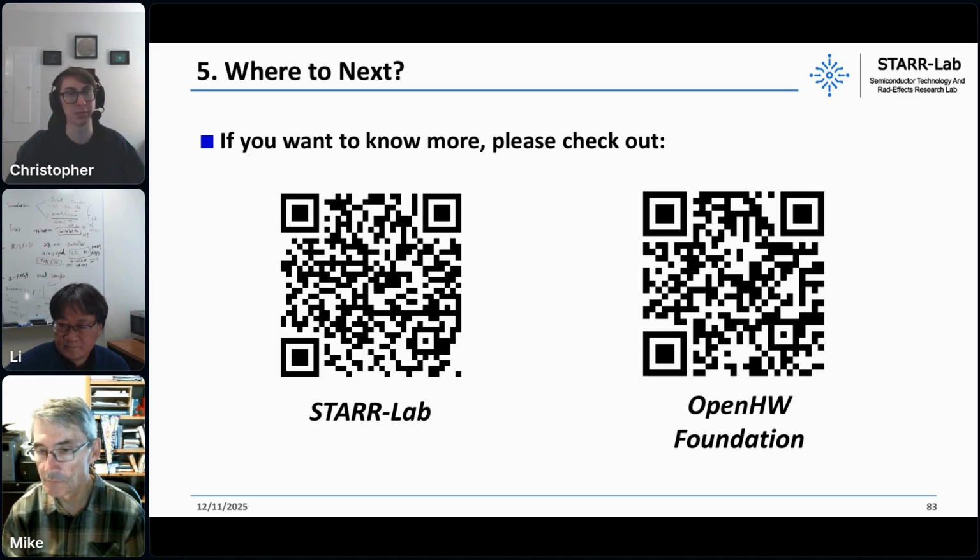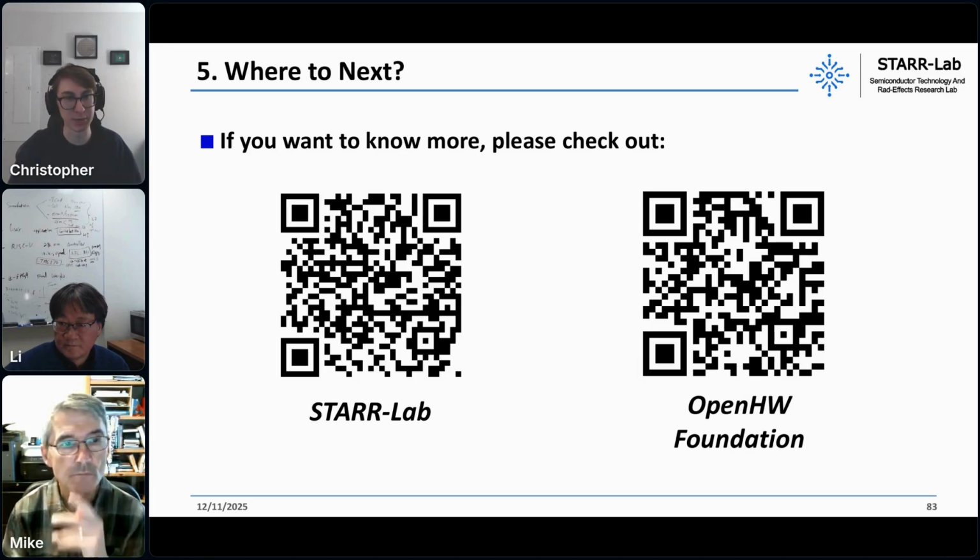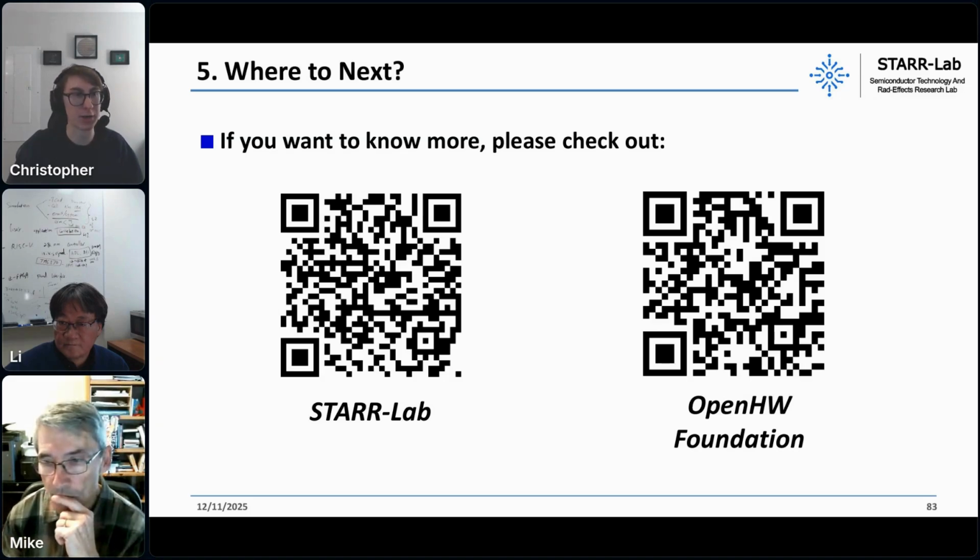Instead of using the ones provided from the PDK in a standard cell library, we're making our own. We have to characterize them for timing and information and everything. But then we're using those in the standard cell libraries, so when the place and route is done, it's using our rad-hardened cells instead of the foundry-supplied normal standard cells. So we're not really changing the PDK. We're just changing some of the most basic building blocks of the device.